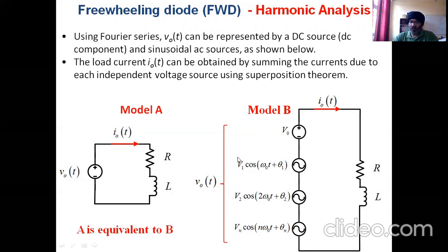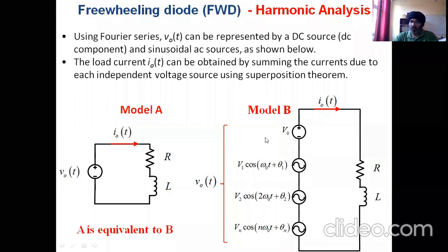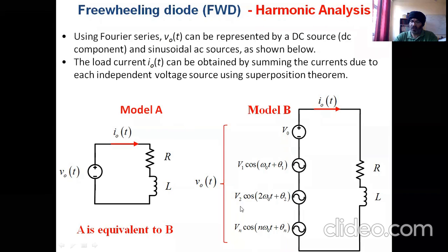Just to explain, if V1 is equal to V0, it means that the DC component we want at the output has exactly the same value superimposed on it, so a high amount of ripple is being superimposed on the DC component, which we don't want. So we first want to analyze, and then get rid of the higher magnitudes of these harmonic components.